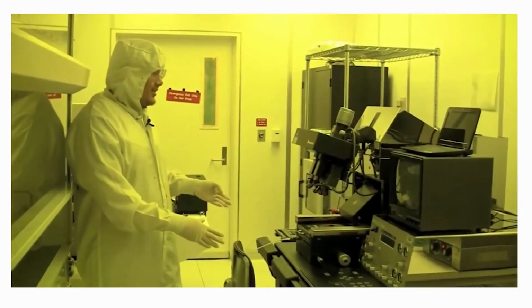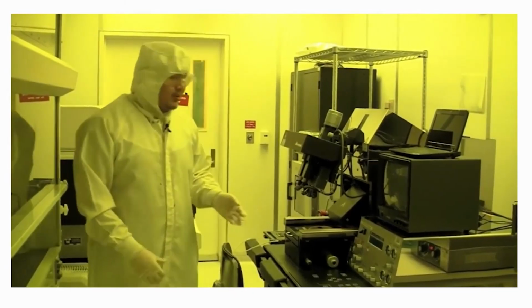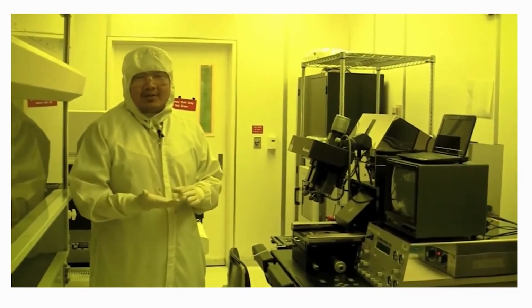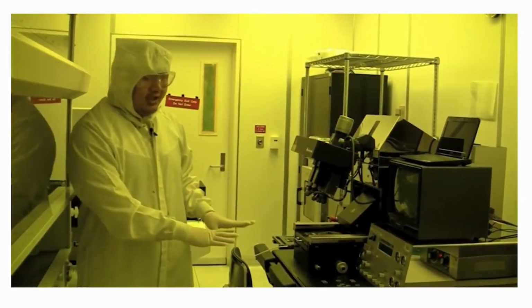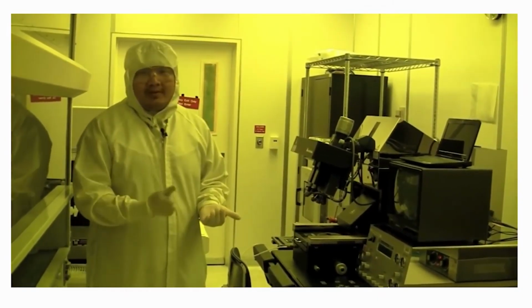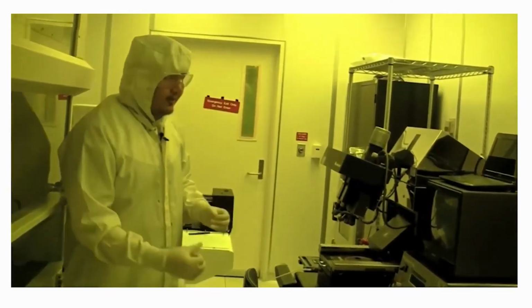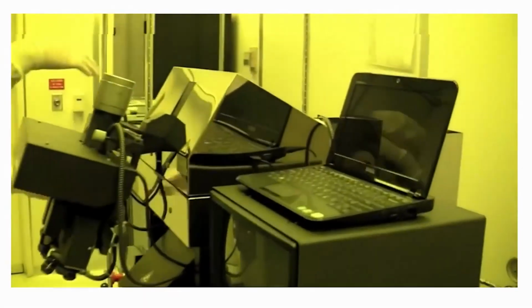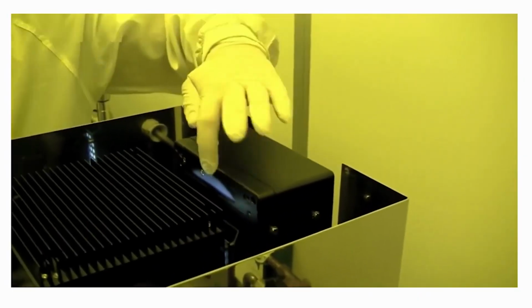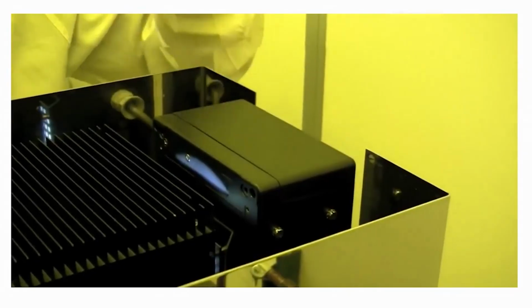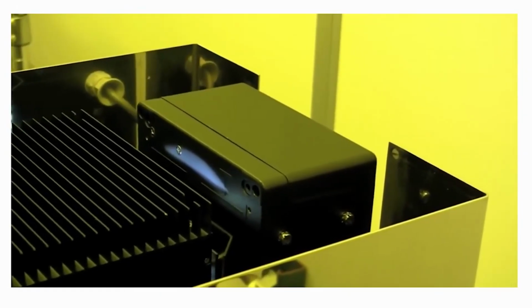This is the MA6. It's used to expose UV light to your substrate that has photoresist on it. So before we run the machine, the first thing we got to do is make sure the light bulb is turned on or even not blown up. So we come out to the back, and you can see the lights turned on by the reflection here, or you can see the light glowing. So you know that the light bulb is on.